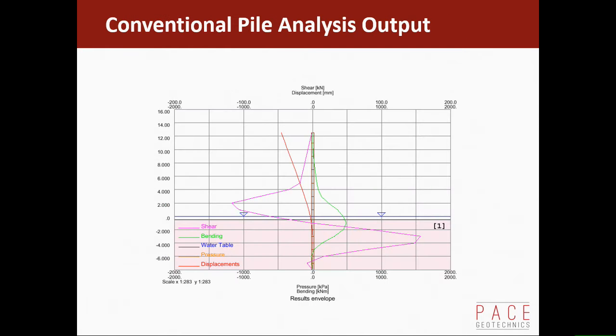And the sort of curves you get, this is for a pile which actually comes quite some way above the seabed, and I think it was loaded there. That's the displacement analysis, so you can see that most of the displacement is occurring close to mudline. The bending moment is always a maximum just below mudline. If you've got a laterally loaded pile, the load is obviously generally applied above mudline.